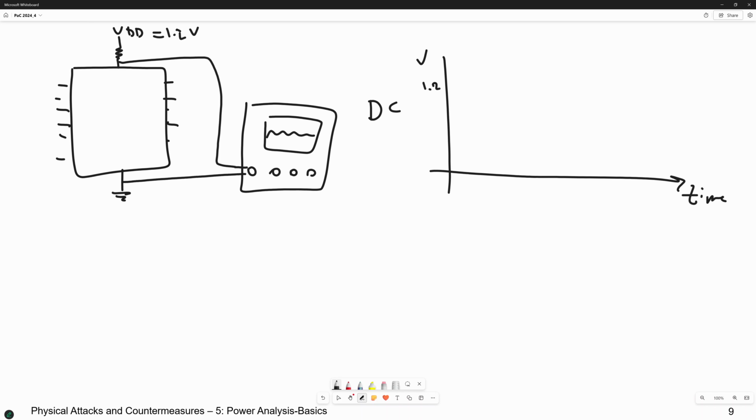And then your oscilloscope should be very good. It should have some features, meaning that you should zoom in on that area and, for example, measure this area with very high accuracy. And these variations are super, super small, in the range of, for example, 10 millivolt. Then not every oscilloscope can do it. And because of this high DC shift, you bring it up here and then measure, then it will be also noisy. Then what we do, you probably have not learned it during your study because you are computer science students. If you have studied electrical engineering, definitely you know it.